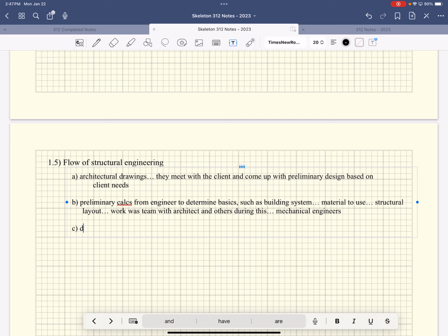And then we have to determine loads on the structure. We're going to learn about these different loads, but there's gravity loads, right? We're seeing called dead loads, live loads. I'm just going to throw in some stuff down here, right? Live loads, self-weight, right? It's just how much gravity pulls down on a structure. When you think of a structural design, that's probably what you think of mostly, right? Keeping the thing standing, resisting gravity, right? And then there's also lateral loads,